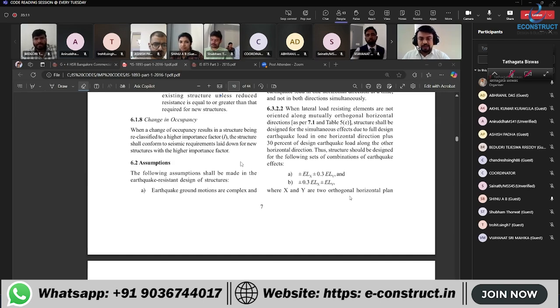But in case of spec Z, it would be AV, which is vertical acceleration. AH is horizontal acceleration, but AV is vertical acceleration. So over there, the formula is a little different, given by the code itself. It would be like 2.5 into 2 by 3 into I by R, and you need to take that into Z by 2. So why 2.5, that also I'll tell you. 2.5 is the maximum value of SA by G. The code has directly told us to take that maximum value only.